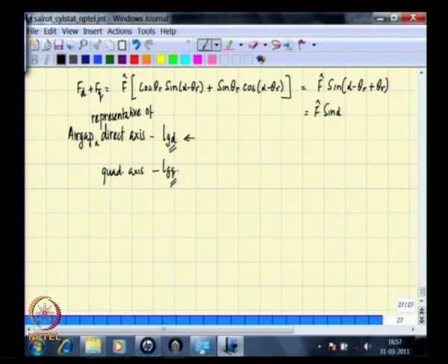Along LGD the MMF Fd is acting, and along LGQ the MMF Fq is acting. So, in order to find out the flux that is generated, we need to divide the MMF by the reluctance.